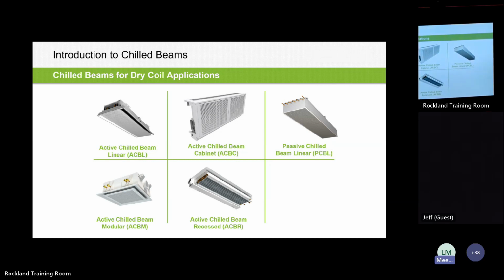There's also the active chilled beam cabinet unit. So these are typically in teaching lab spaces or classrooms where you put them underneath the window areas and provide cooling and heating and deliver the air actually in a displacement ventilation pattern. Have you heard of displacement ventilation before? The intent with that is to actually stratify the air, not de-stratify, and allow the heat loads to pull the air throughout the space instead of being pushed and churned uniformly throughout. So that's kind of unique and neat because you get the benefits of the decoupled chilled beam system, but also that displacement airflow pattern. So that's commonly used in